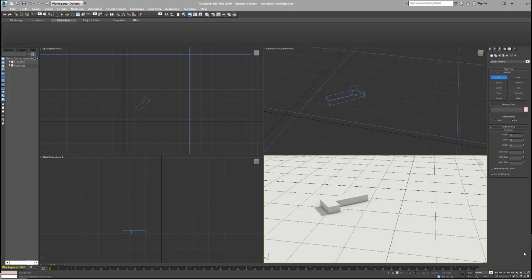I've set up a 4-point viewport here using Alt-W. If you're not there, it'll just reset your viewports. I have a perspective window here. I don't yet have a camera in my scene. Perspective here in wireframe mode so that I can monitor what's going on. I have a top view and a left view. And this is a scenario that I'm comfortable working with. Sometimes I'll switch back to that full-on using Alt-W, or I'll go back to that default workspace and I'll maximize that out. You can also switch in 2018 your viewports in this lower left-hand corner. So just a little bit of review on that.